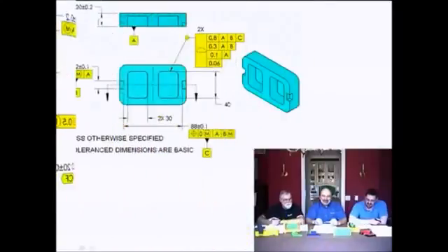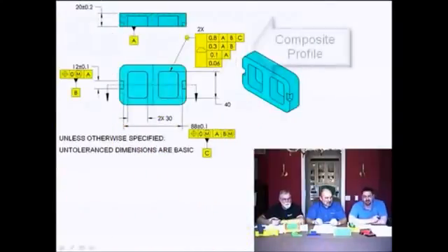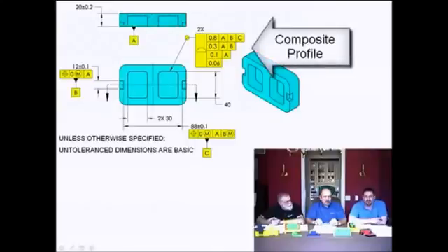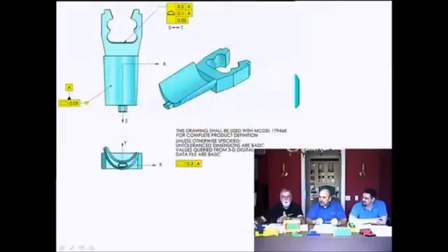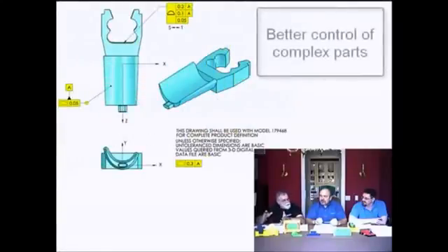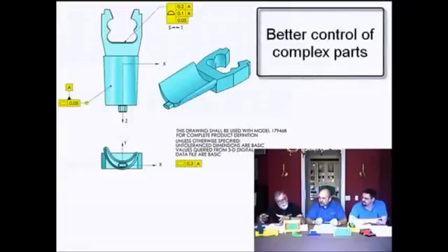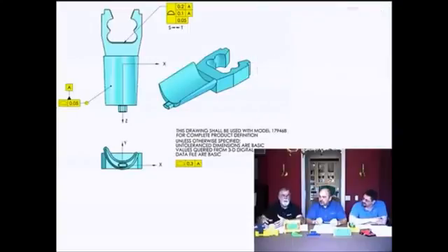They've also expanded composite controls to include pattern controls with surface profile. And Frank, you were saying something about it appears that the standard has been revised to keep up with technology. I think it has. As technology's changed over the years, CMMs have gotten better. We can measure tighter and tighter tolerances. CNC machines have gotten better. We can achieve tighter and tighter tolerances on parts. So therefore, our standard, Y14.5 in 2009, is trying to accommodate that.